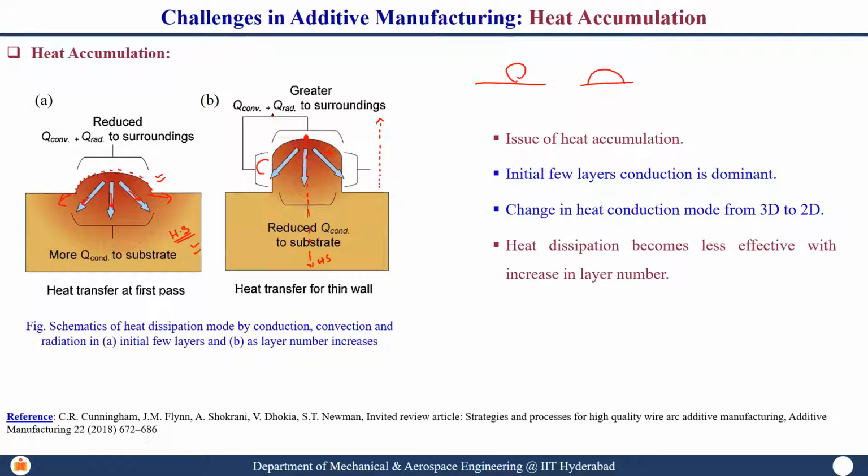accumulated. This is the major cause which is creating all sorts of problems in additive manufacturing, whether it is powder bed fusion, laser DED, or VAM. In case of VAM, it is slightly easy to control this, because you can use a gas jet, you can use a mist and all those things. But when you are blowing the powder, you cannot use all these things, because parallelly the powder will also get blown away. So indeed it is much more complex to control this.